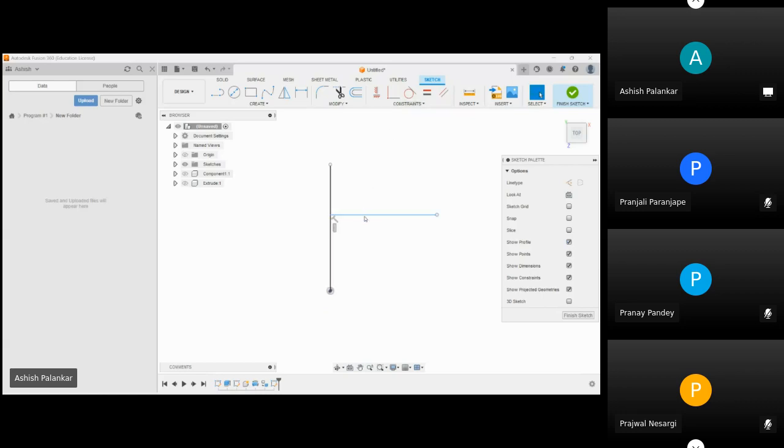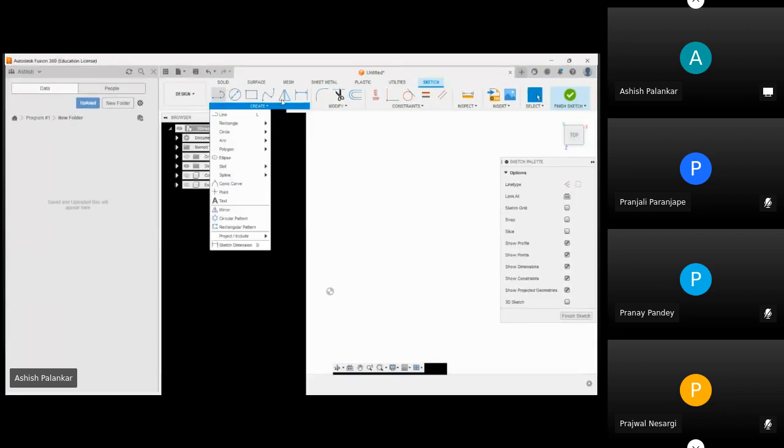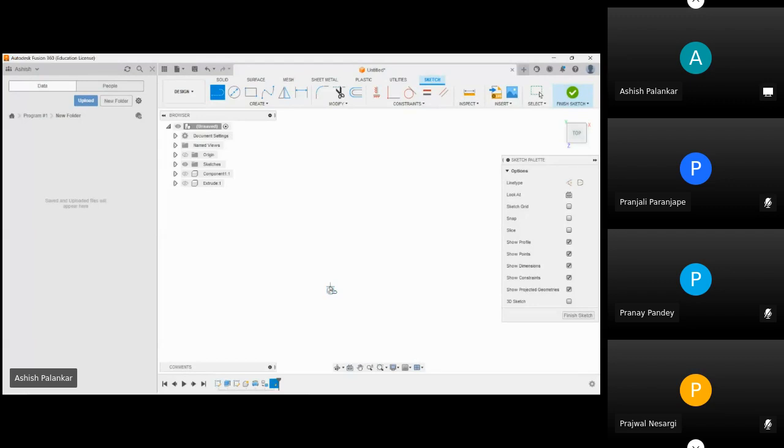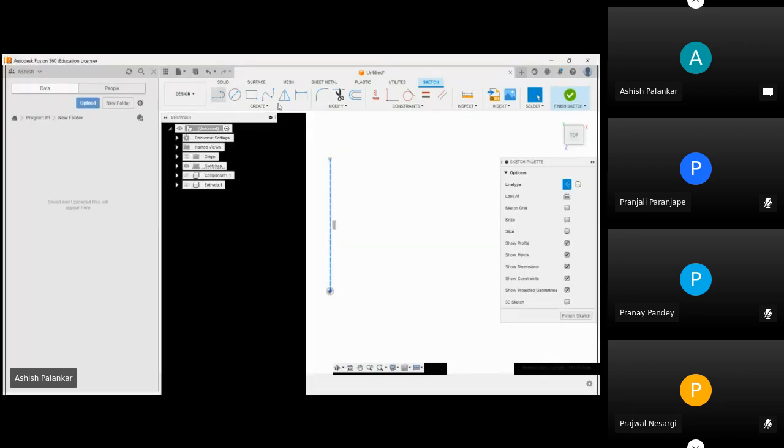Right. So select all. You can also click the left mouse button and drag like this, then just delete these sketches. Now we will go to the symmetric part. Like if you create a line, let's create a construction line. Create a line, press escape, select the line and press X on your keyboard.